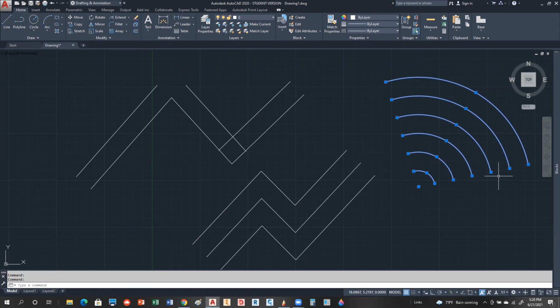Very powerful. If you've got parallel objects, like let's say you're building a floor plan or something, with a lot of parallel lines, wall lines, offset, you draw one outside line and you just offset things in, offset things out. It's a really powerful command. And so let's take a look at the option through, okay?